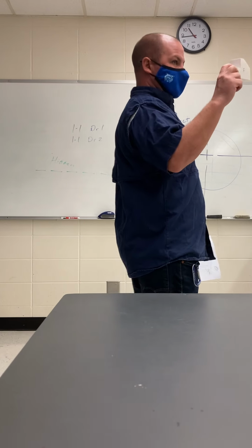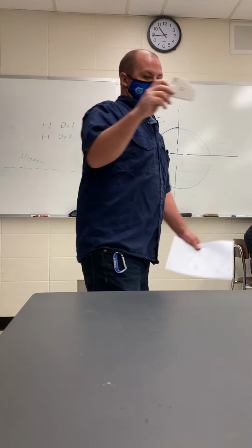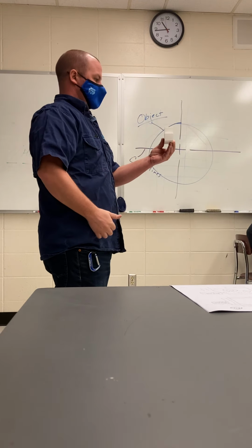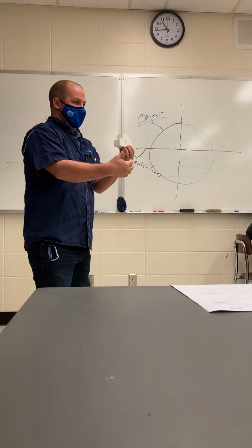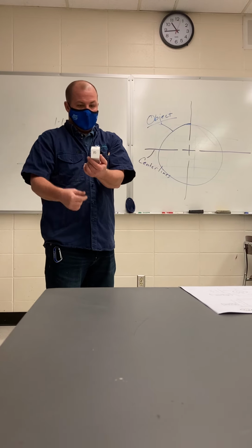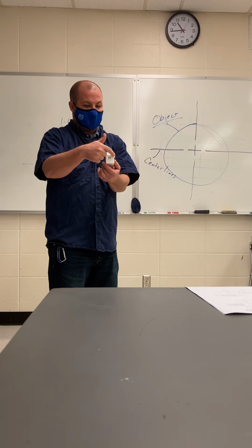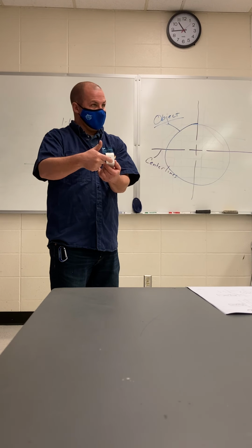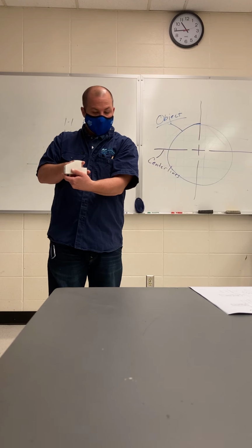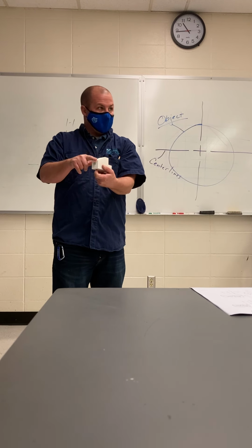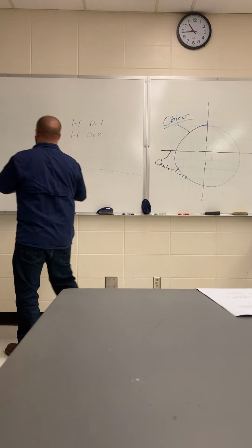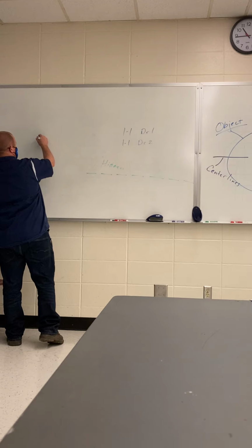Okay, you got a part like this. Everybody can see that I got this angled chamfered front. Now if I'm looking at the right side view, so if I turn it so that I'm looking directly at that camera, I got a line here because this surface and this surface meet. That makes this line. But back here I got this little notch out, right? That's not at the same height as this. So what, in a real world, that right side view would look like,